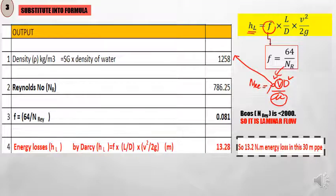So substitute it and you will get your Reynolds number. Once you get your Reynolds number, you substitute into the equation for F here, and then you will get F equals 0.081. Once you are done with F, you just substitute into this formula.